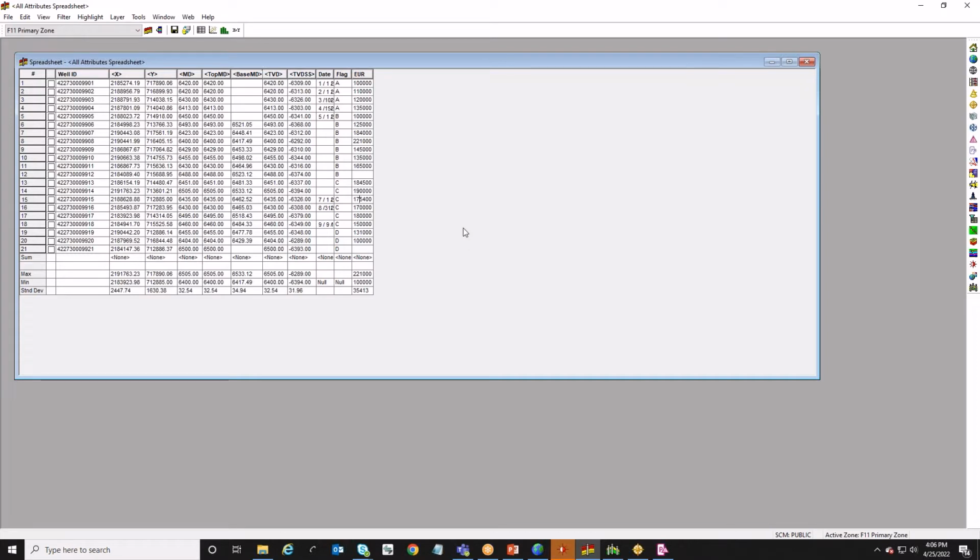There's no field or table for it. So Zone Manager is the place to put that. It's all user-defined, user-created. So you can kind of set this information up to be however you want it to look, how you want that data to be, whatever attributes you want to put in there. It's all up to the user. Everything's user defined. Okay. So yeah, just bringing that data directly in from that spreadsheet into Zone Manager. Pretty simple to do. Just map out what attribute it's going to, create those attributes as needed, and then populate that data there within the Zone Manager.